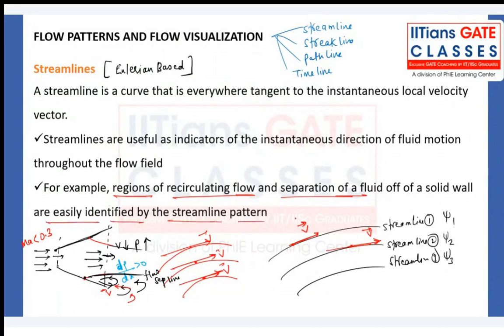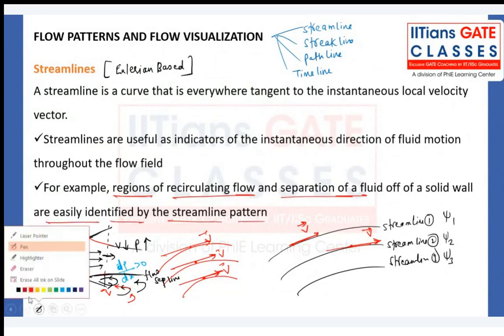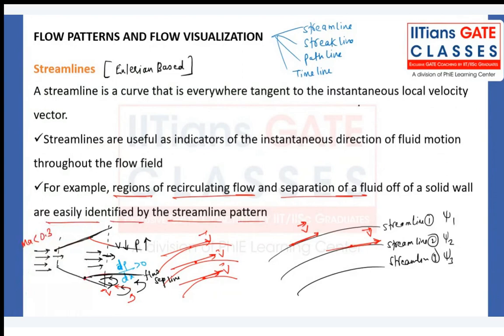Whenever you do any simulation in CFD or ANSYS Fluent, whenever you have a CD nozzle or combustion chamber, when you do the analysis, you will come to know this flow pattern behind the diffusers, right? And that will become a wake region of very low pressure. Why low pressure? Even though we are saying that high pressure is there at the back of the diffuser section, still this recirculation region is a low pressure region.